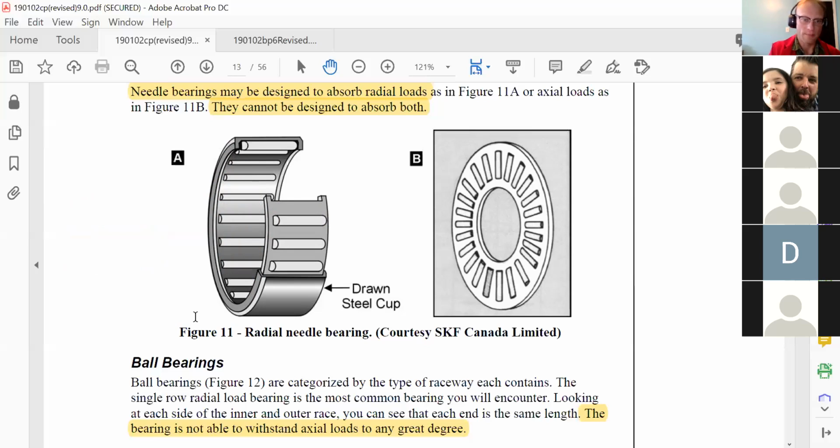The reason that happened is they look like they're the same, but they're not. I would have to draw a better picture. The needles in a U-joint are slightly tapered in one direction, so they aren't a perfect cylinder.